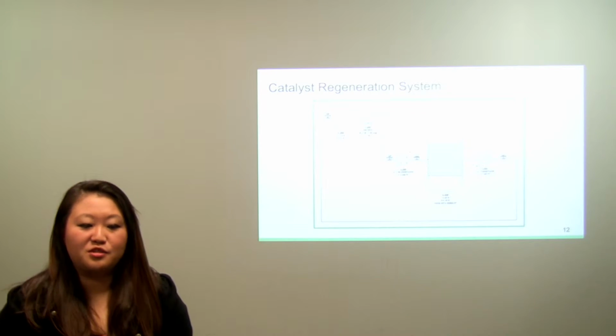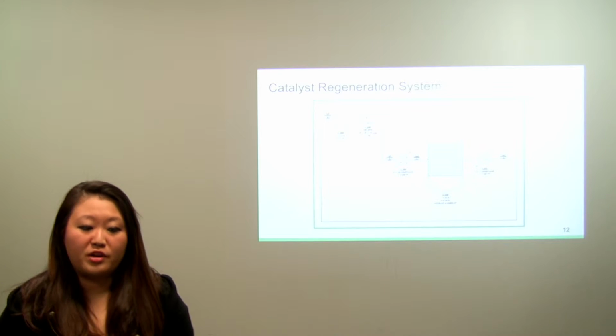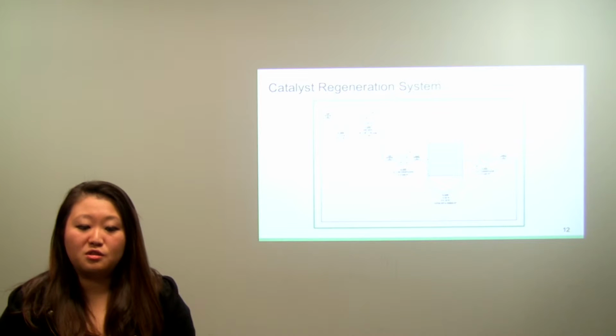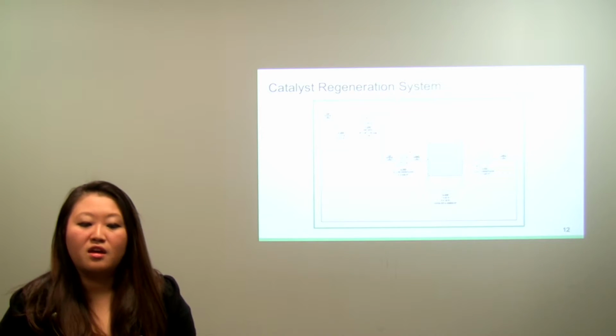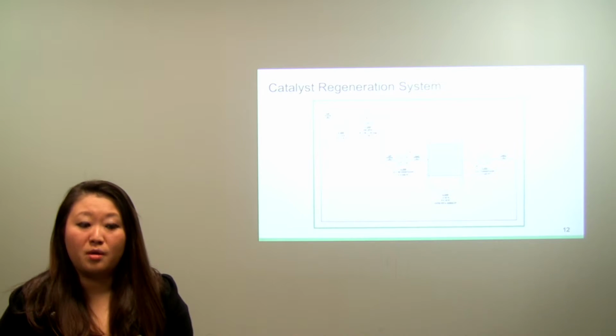Another side process that you do not see from our BFD presentation is a catalyst regeneration system. During the operation, the coke forms and gets laid down in the catalyst pores. Due to this fouling, the catalysts in V100 have to be regenerated every 30 days by coke burn-off in a steam-air mixture. The coke deposit amounts were assumed to be 1% of the catalyst weight after 30 operational days. The total regeneration operation including shutdown, purging, burnout, and startup takes about a week.